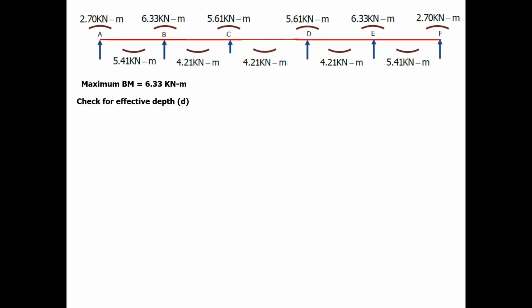Sir, D required is equal to root of M divided by 0.138 fck b. So calculate the value.